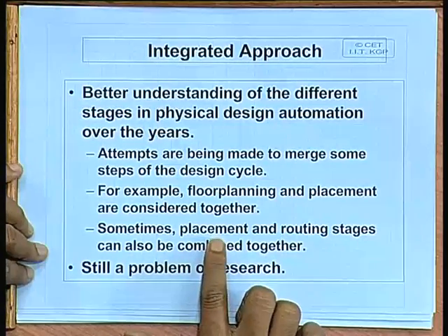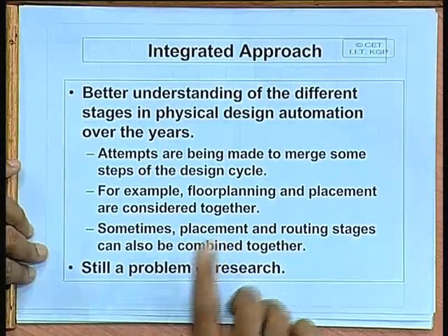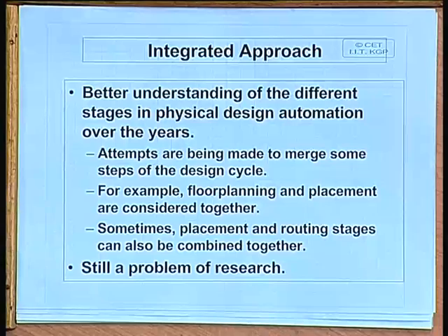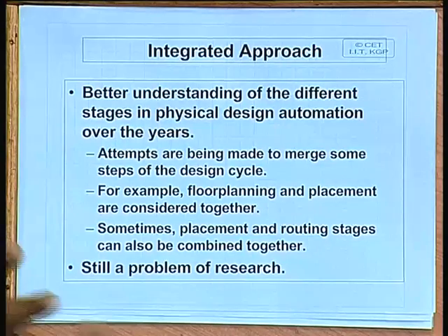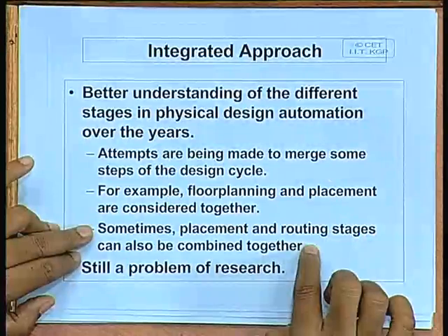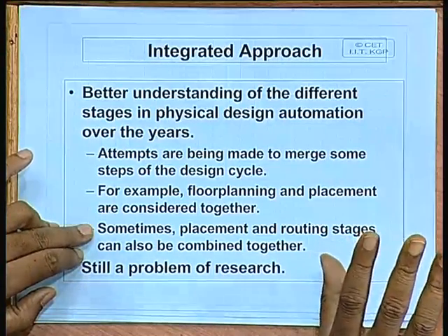Of course, some estimate is already done during placement, where you evaluate a cost function so that routing complexity is less. But since you are already spending some time, if you can spend a little more so that some of the routes also get established, it helps in the later routing steps.